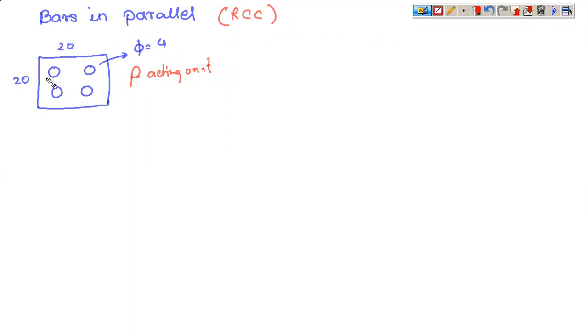But right now, this is a system of RCC where you have 4 rods and you have an RCC block. RCC means a concrete block. Now these are in parallel. So if you again apply the concept that we have seen previously, you can say that the total load P will be distributed in such a manner that P of concrete plus P of steel, it will be distributed evenly, not equally. It will be distributed evenly. That means on the basis of ratio of strengths.